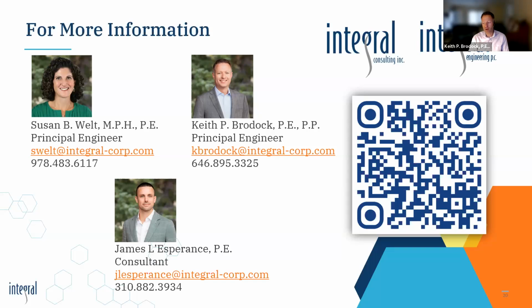We've got another property we're working on right now. They have a recording studio on the first floor. They don't want any equipment with moving air anywhere near their recording studio because it's going to throw off all of the acoustics. And so we need to make sure that we're taking a very creative approach there. We are burying pipes, we're going outside, we're going up the outside of the building, and we are trying to locate the equipment on yet another property so that there's even less of a chance of vibrations and noise and anything that could disrupt that studio.